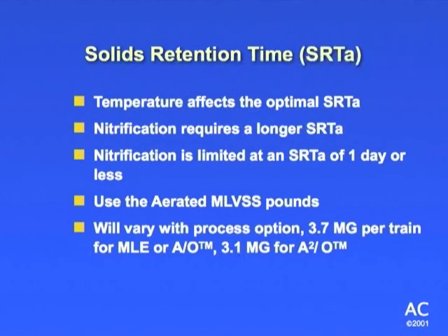Temperature will affect the optimal solids retention time, because what does temperature affect as far as your process goes? The bugs, the activity of the bugs. So you got to take that into consideration that, hey, I've got this at the design SRT, but then you say, well, wait a minute, we've been having 90-degree weather for 2 weeks on end, going through a horrible heat wave, and the water's really getting warm out there, so you have more activity.